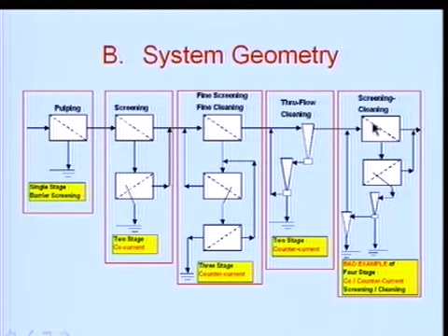And here's a four-stage modified system where the screen accepts go forward and whatever is rejected is treated by reverse cleaners and forward cleaners, again to preserve fiber balance. Again, this one here is a bad example, a mixture of co-current and counter-current screens, but I have seen this in mills. It is being used. Is it a bad one? Yes. Can it be functional? Yes. So all the answers are possible. However, if you can avoid it, it's better off.